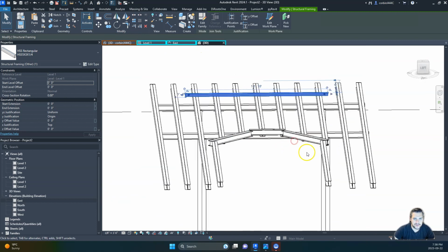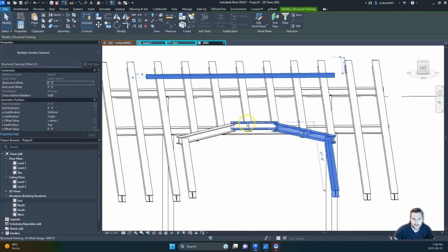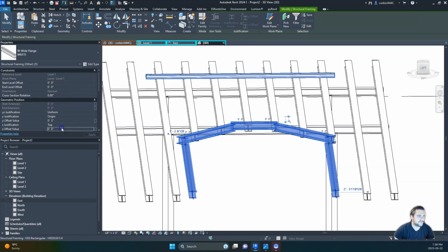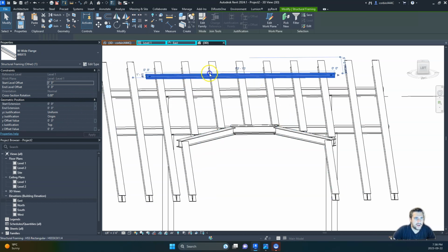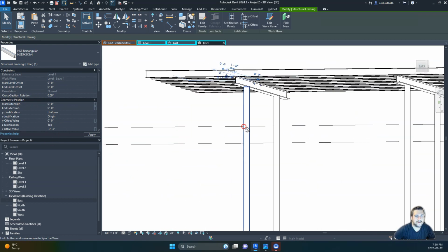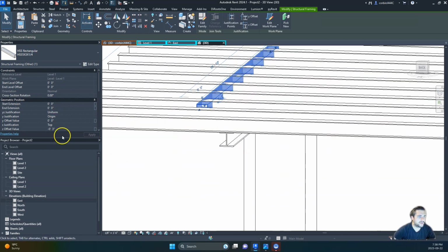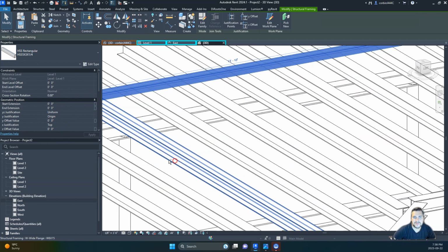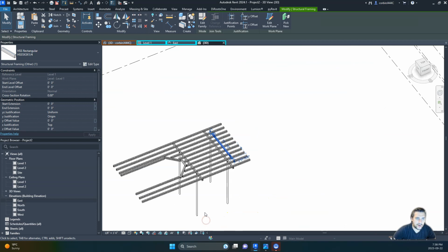And then the last thing we just need to do is these need to go down the 3 inches that we did before. Shift that one, so this will go down -3, and that's at the same level now. This would actually be down -3 as well. And oh wait, actually no, it's not down -3, it's 0, because that's sitting right on top of the steel like that. So that's how we model a dock. And so it's very different on every project, but that's the general layout.